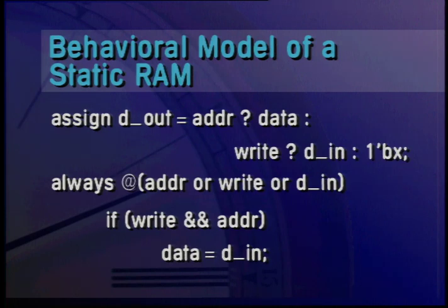The interesting thing is that in many cases, the bidirect is being used simply as a notational convenience, and the logic of the model allows it to be replaced by a unidirectional primitive, which will simulate much faster. For example, a bidirect is often used to model a resistor, which can be modeled with a unidirectional primitive. It is often the case in an HDL that if you use a more general construct than necessary, the simulation will be slower than it could be.